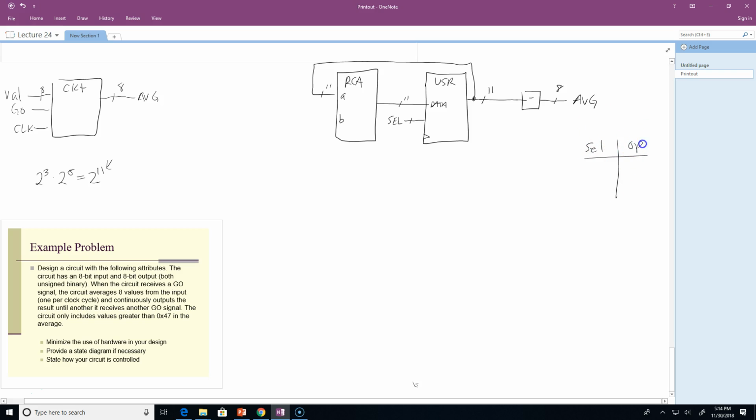Operation: 00, 01, 10, 11. These are the 4 possibilities of a select: hold, load, shift right, shift left. Okay, that looks good. And by all means, I know this is something I'm accumulating, so I want to be able to clear the shift register. Looking good.